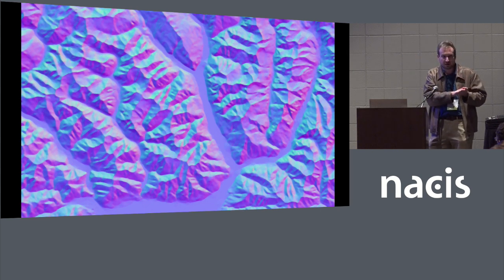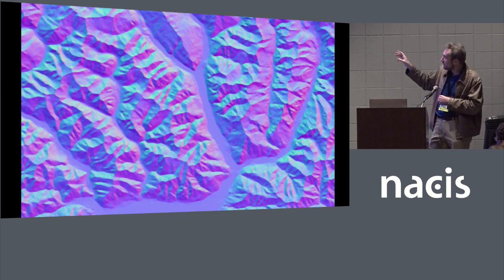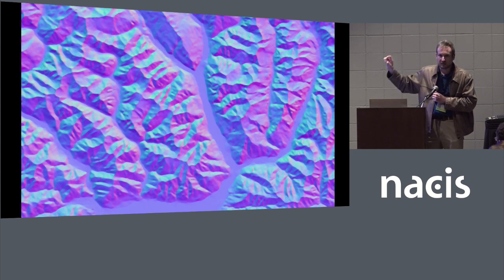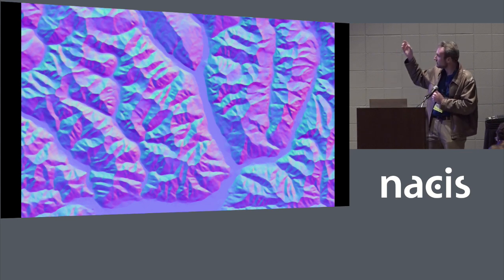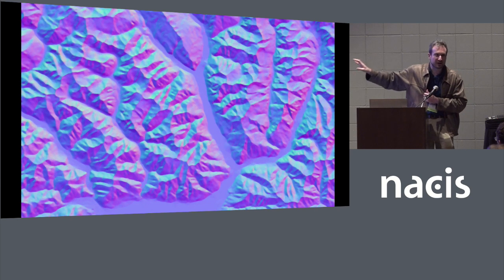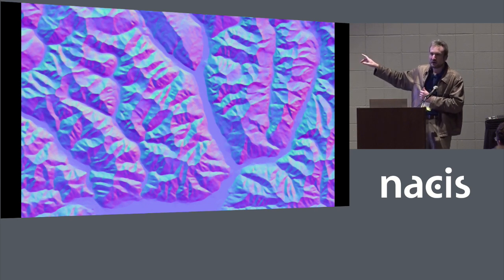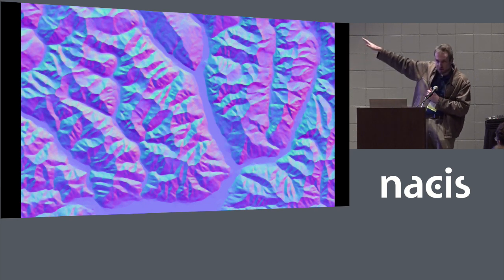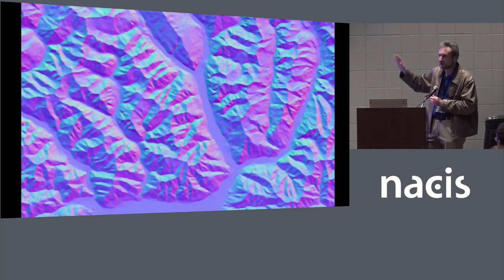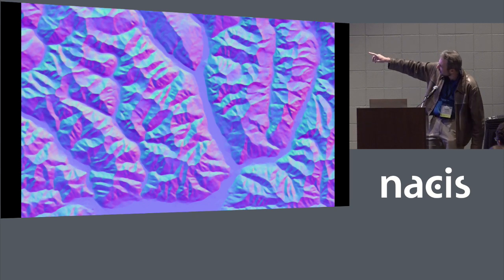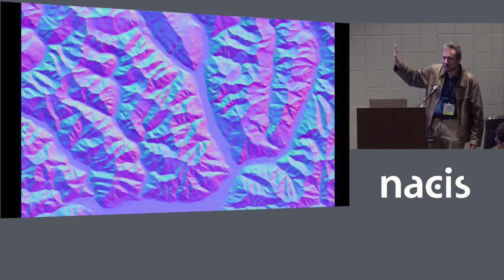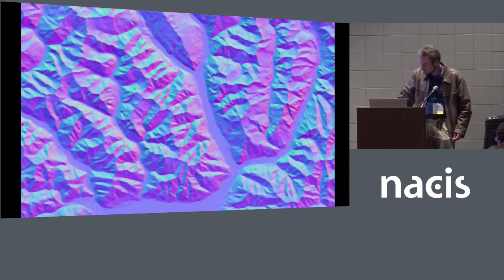small differences in orientation. On a normal map, you can do something that you can't with a DEM if this is your goal, which is to use median filters and high pass filters on the normal map to smooth out those small changes in orientation, but keep the major differences. I've done that here on this normal map, so you can see I still have those sharp ridges, even though the details on any given face have been smoothed out.